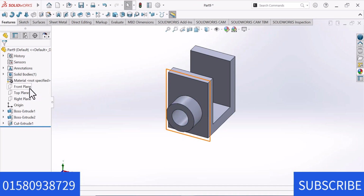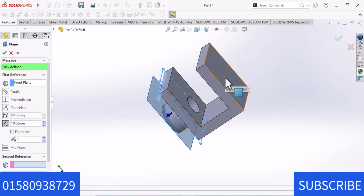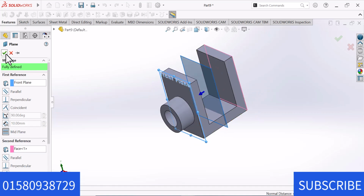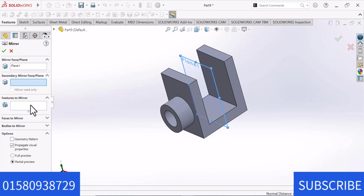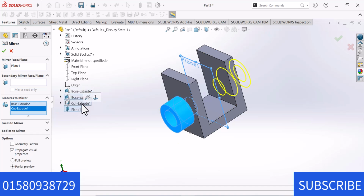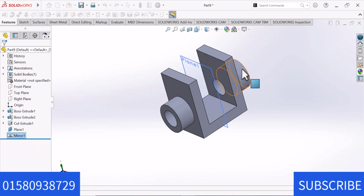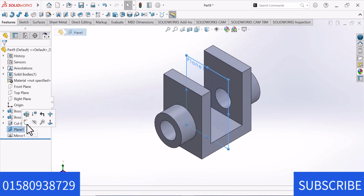Now go to front plane and Reference Geometry, Plane. Select here. Okay. Now go to select Mirror. In Mirror, select the features to mirror: here select Extrude and Extruded Cut. Okay. Now go to isometric view. I am going to hide this plane. Okay, we have made our job.